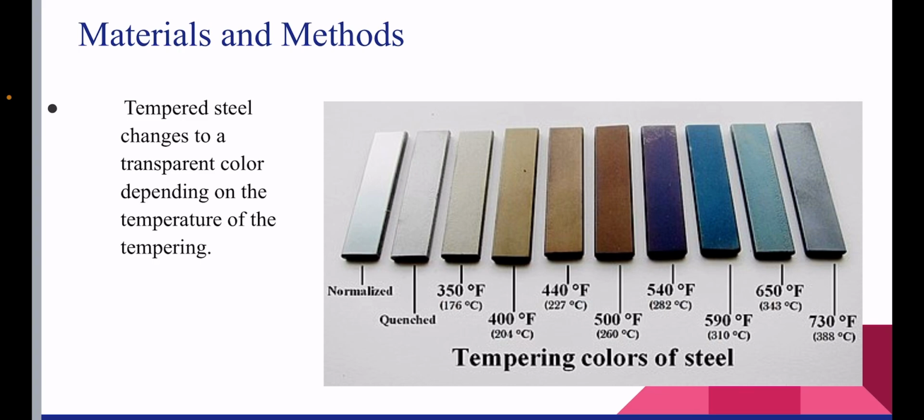The color itself is actually formed by an oxide layer. It just forms on that surface. Higher temperatures create thicker layers of iron oxide, and so do longer time frames spent in that temperature zone. The layer actually does help to prevent the steel from corrosion.